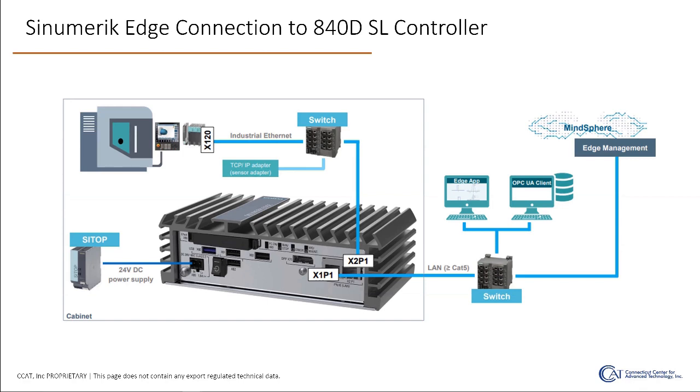And if that network is connected to the internet or has access to the internet, then we can access MindSphere, and we can download applications from MindSphere onto the Edge device and install the application on the Edge device. Otherwise, if we're just connecting it to the network for the sake of accessing the interface, we access the Edge device interface by bringing up a web browser, typing in the IP address of the Edge device, and then we can get the interface so that we can configure any software that's installed on the Edge device for the purpose of data capture.